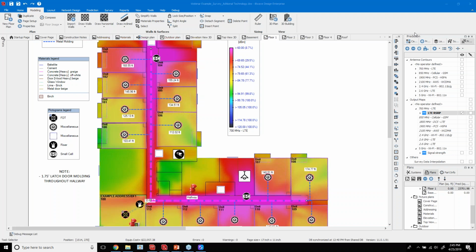Okay. This question is, can we connect more than 32 splitters at the final building location? So if you are operating over a GPON network, which it seems like that's the assumption, and you've got a 1x32 splitter, what happens when you have a 33rd customer? You have to add an additional splitter, which would mean you would need an extra feeder fiber servicing that splitter, and you'd also need an extra port on your OLT back at the central office or head end.